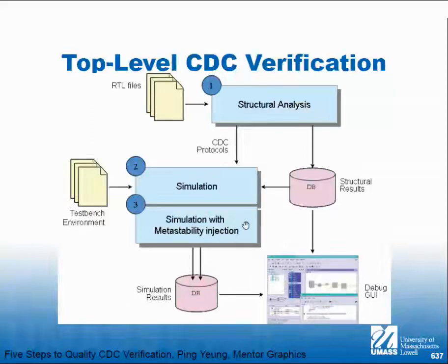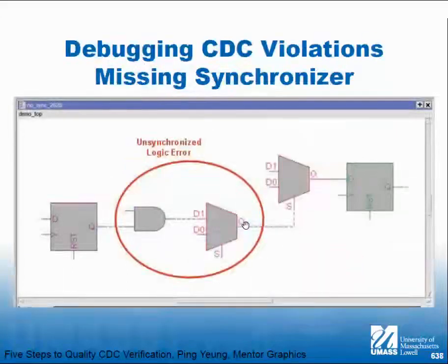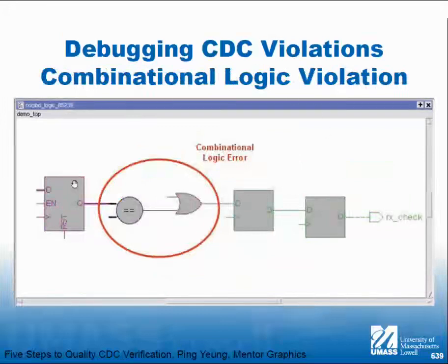Simulation metastability injection is hard. And I say it's hard specifically because if you have 100,000 flip-flops in the design, you don't have to do it on all of them, but if you have 200 signals that pass between the two, there's 200 places where a CDC event could happen. So if you have logic in between, you can have errors in the logic. Important to know. I'm going to sneeze, sorry.